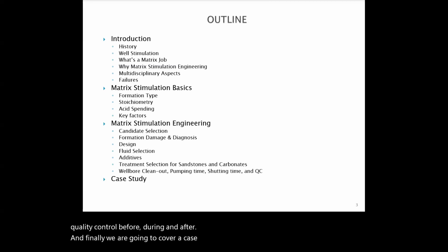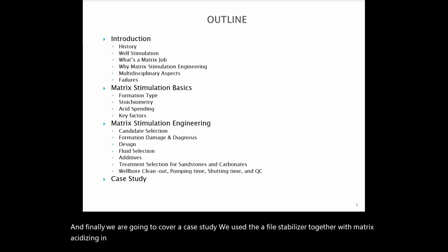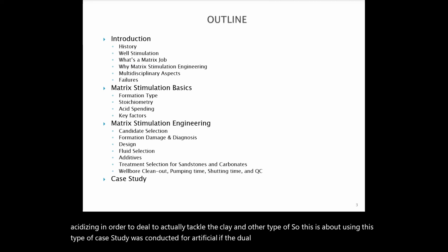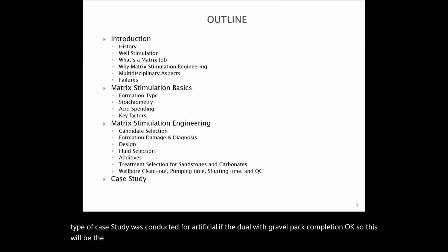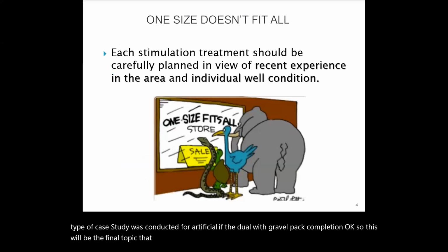We used a fines stabilizer together with matrix acidizing in order to tackle the clay and other types of damage. This case study was conducted for an artificially lifted well with gravel pack completion. Okay, so this will be the final topic that we will cover in our course here.